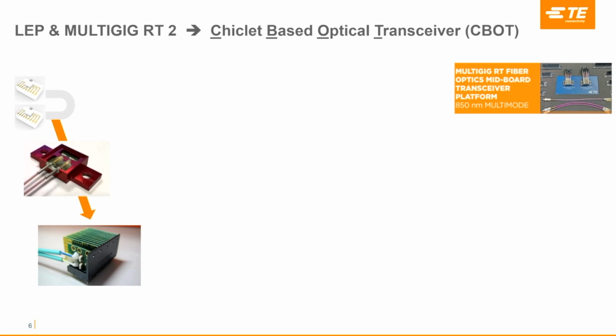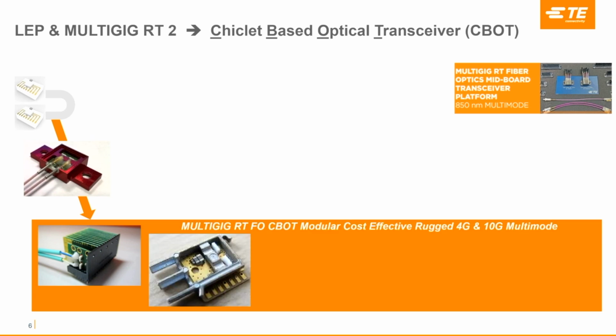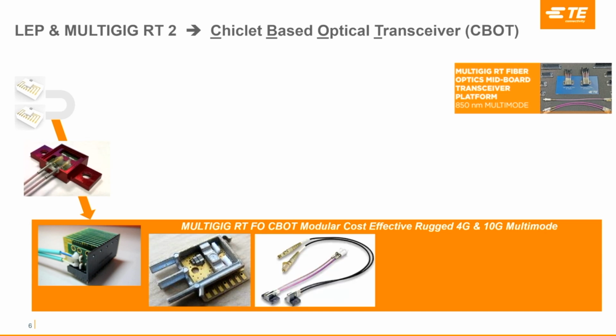Well, so now what happens is the science project that you see at the bottom, where you basically took those optical engines and mounted them on one of those circuit board wafers, you now have a 10 gig transceiver, okay? So that becomes, with a lot of work and effort on the part of the design team, ruggedized well enough with the appropriate hardware so that now when you install this in the middle of a system and run fiber pigtails to, say, the output on your box, you've got resistance so you don't pull these things out of housings and what have you.